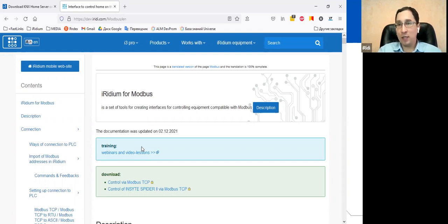I mean, this device is not available on this bus, and it means that the driver, when asking this device "how are you", is just waiting for a timeout, and this timeout is like 10 seconds, a little bit more, and it looks like a freeze.